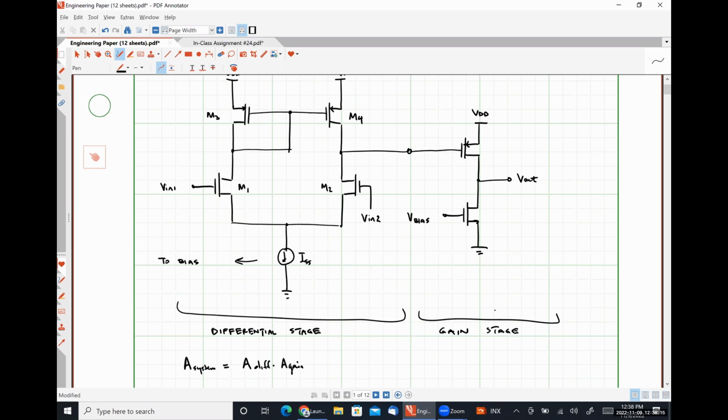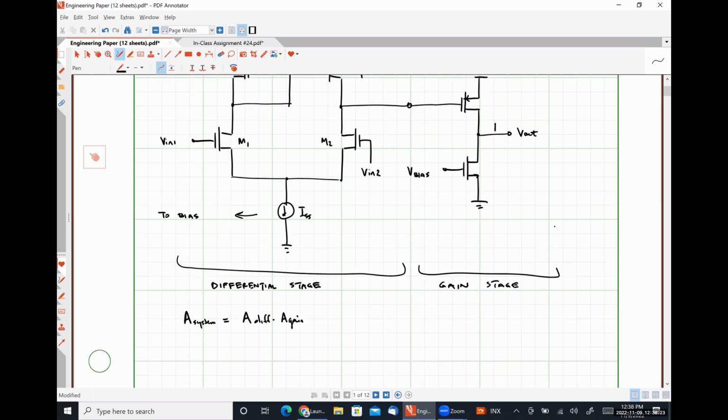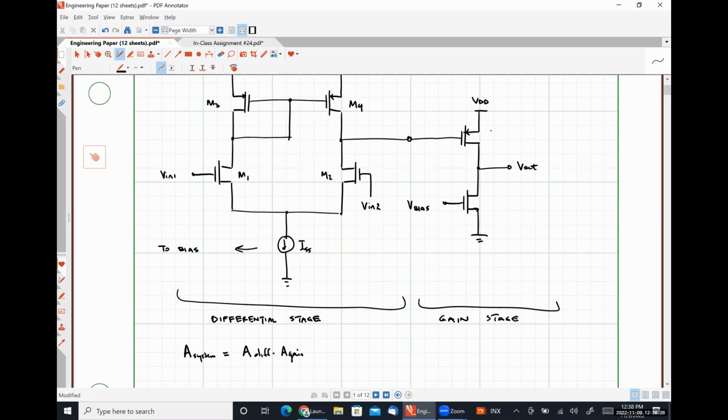Common source. Absolutely right. Common source amplifier where the PMOS transistor, so let's call this, my screen would stop sliding away from me, MCSP, and this guy will be MCSN, for common source PMOS transistor and common source NMOS transistor. The CS here doesn't stand for current source, even though the NMOS transistor is behaving like a current source. Anyway, just wanted to clarify that.